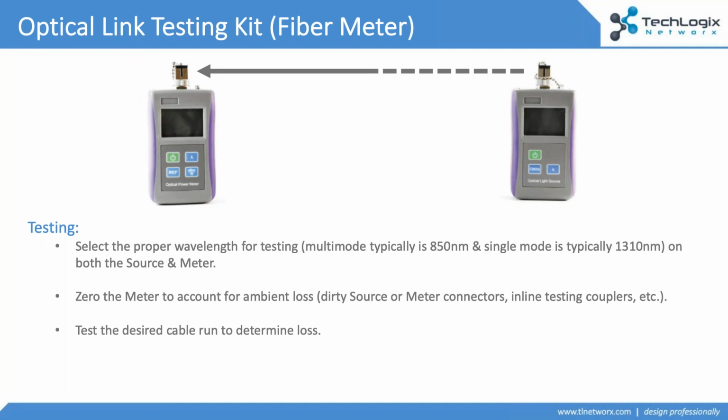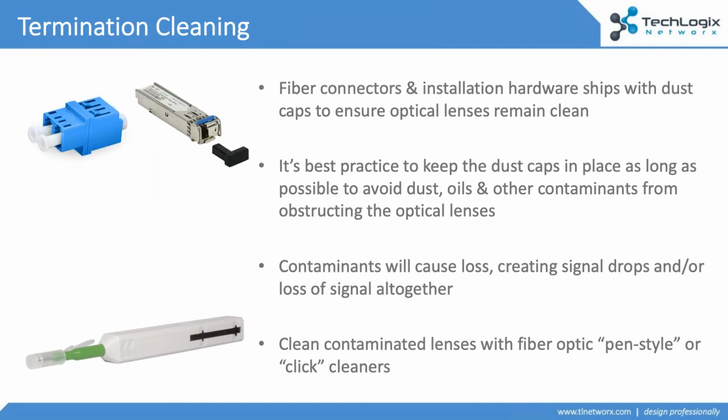And two, every time you plug and unplug a fiber optic connection, there's the incidence for wear and the incidence of getting things dirty. So really great practice is just using an inexpensive little 1 foot, 2 foot, 3 foot patch cable, zero that out of your system, and then you're good to go. So just a little process I recommend as you're working on metering.